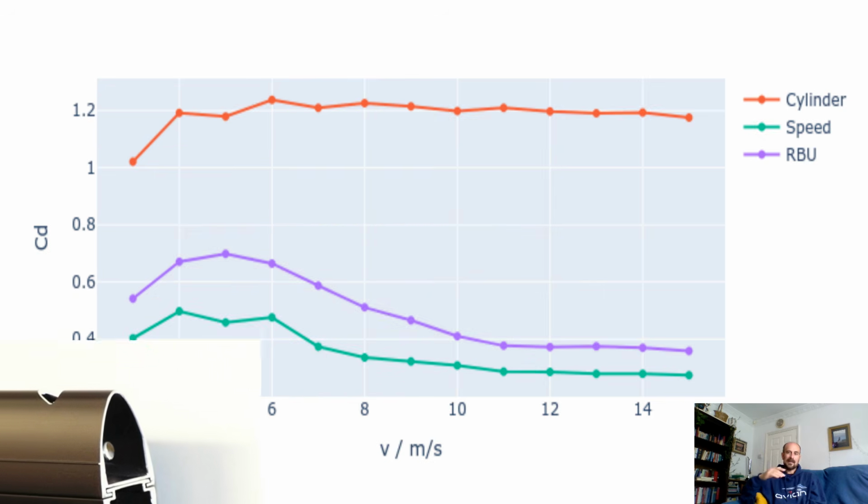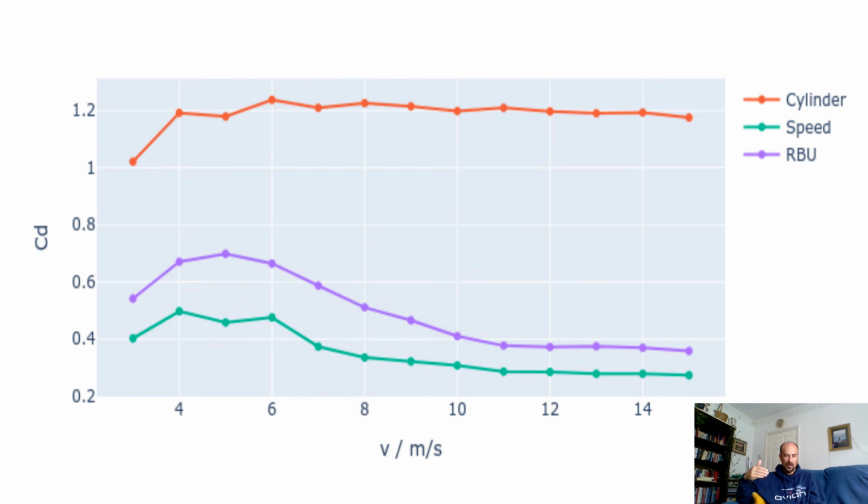As you start to increase the speed, you'll get turbulence starting to build up, large scale turbulence. If you get above a certain speed, then that turbulence starts to collapse and wrap around more, and the turbulators can make that happen at a lower speed.